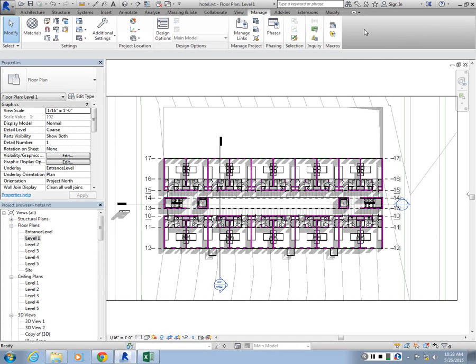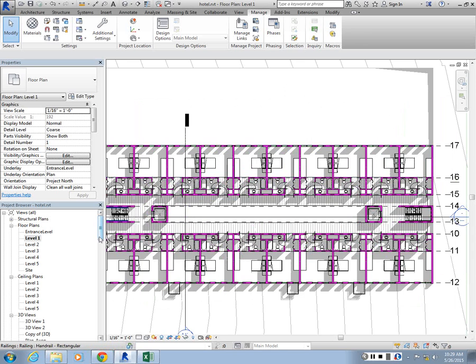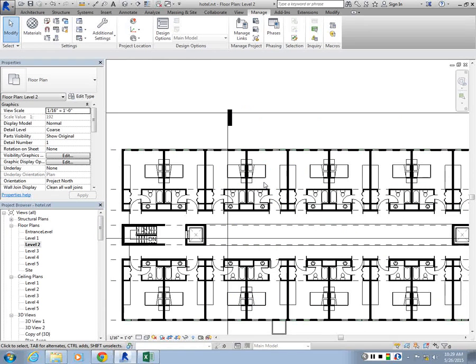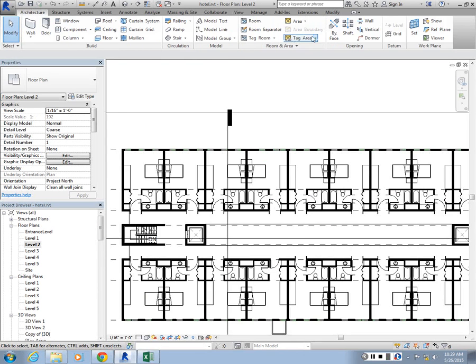Like when you have the floor parts, each part would have its own material, surface pattern. But then for the room, when you create a room, you do the shade for the room. Is there any way to have both? It seems to have either one or the other. So you're doing the floor pattern through the parts, but you also want to create a room. Yeah, right. Like the room poche itself.